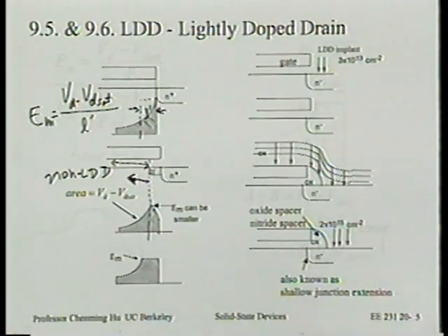Now remember, in what I'm saying, I didn't even particularly call out the channel length. The channel length turns out is important because of packing density. But whether it's another 200 angstrom shorter or not doesn't change the packing density that much. So suppose you actually can satisfy that goal of very high performance and good reliability, even though your channel length is just a tiny bit larger than competitors, you still are okay, and you may actually should be considered a winner. But in reality, it's known that in order to get high speed, you want good current and low capacitance.